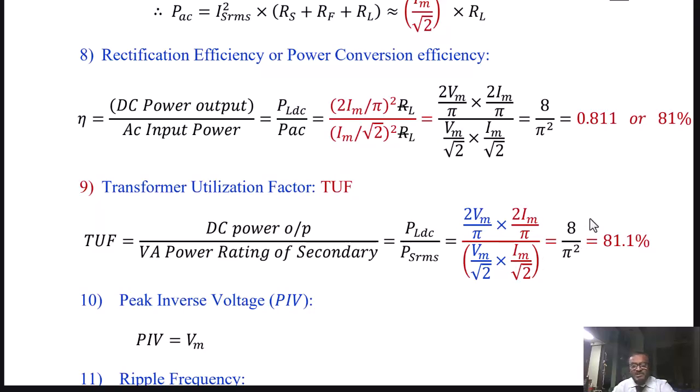And therefore, the bridge type of configuration of full wave rectifier is more popular in practice since its transformer utilization is good, and it only needs a single secondary winding transformer, and therefore the bulkiness of the supply section will be less. And that's why the bridge rectifier will be the obvious choice for electronic circuit power conversion stages.